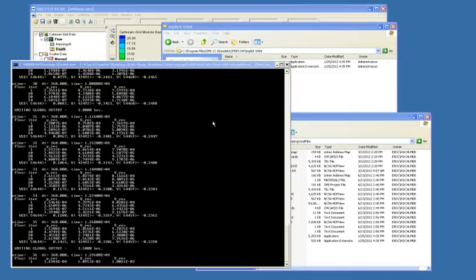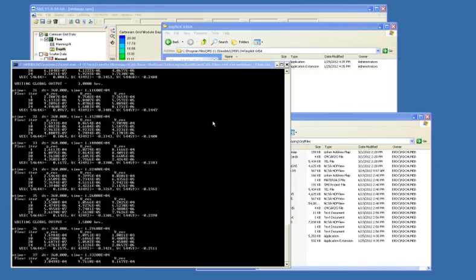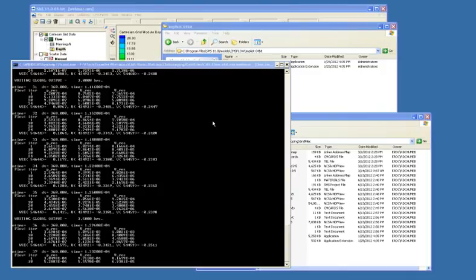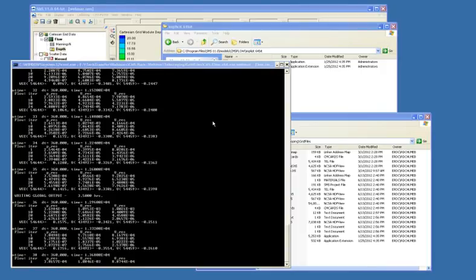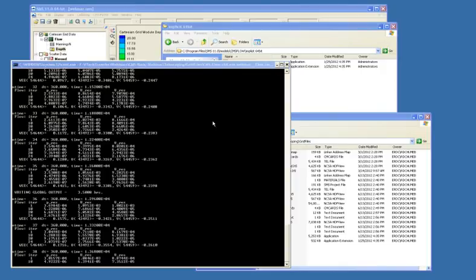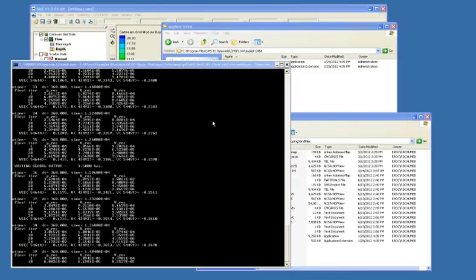Another question, probably the last one or two before we finish for the day. Can you use a wave generation model such as WAM to generate deep water waves at your boundaries? I believe the answer to that is yes. You'd have to find some way to generate information from WAM to be able to apply to every cell in the grid. There may be other ways to do this that I haven't thought about. We're going to be covering waves tomorrow, and so I may reserve this question for tomorrow and ask our wave person, who I hope will show up tomorrow, to answer this question.